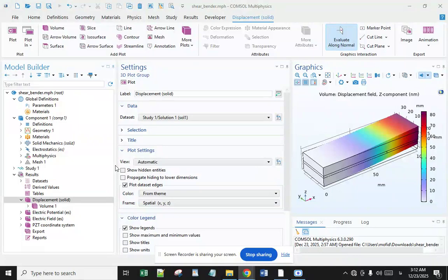As can be seen in this simulation, the surface-mounted actuator is more efficient when its stiffness is greater than the structure's one. Nevertheless, the sandwich actuators are not so efficient in this case. They preserve their effectiveness in all their range, especially in the most common structures. Actuator stiffness ratio ranges between 1 and 10.